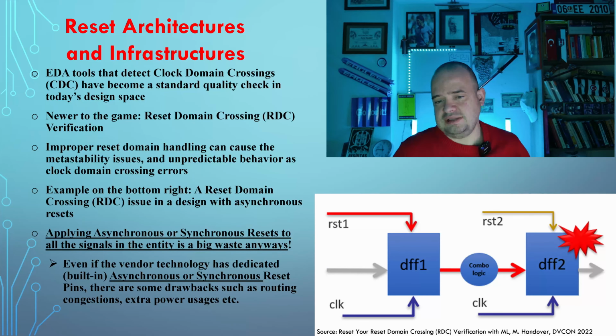So for instance, for such families and some similar families, it really makes sense to use asynchronous reset most of the time. As I said, by the way, not using reset is still an option. As long as the signal you defined does not require an immediate reset value, you are not supposed to use reset. But I am mentioning it here in case you need that reset value, then you need to check your FPGA family and your resources. That is the approach.